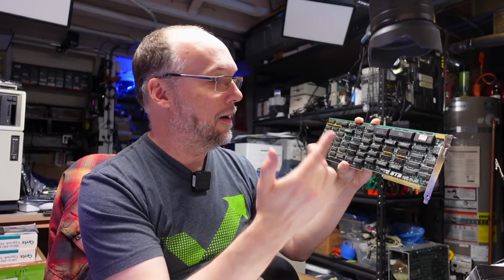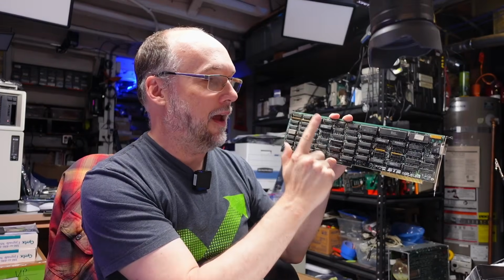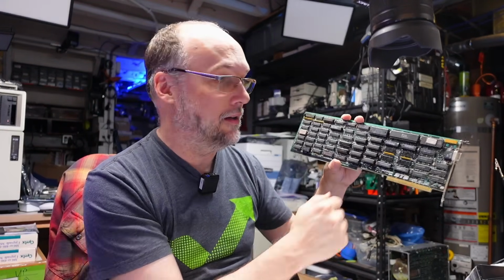And like I said earlier, I'm pretty sure that the bad signal, besides going to this PAL chip and this other 374, must have gone somewhere else on the board that I didn't find. To be honest, I didn't really look at these other PALs over here, and it probably went into one of these that forms the graphics engine of this board, like creates that bitmap graphics.